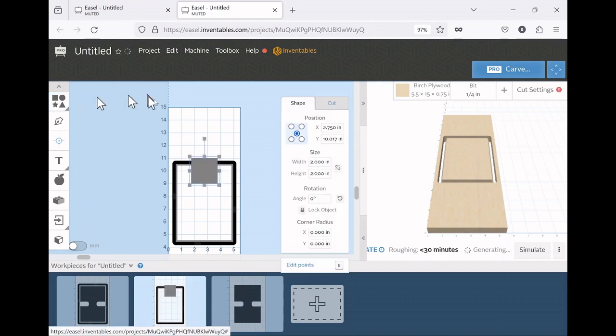All right, we're going to now cut out this area in the center, and we're going to do that by creating a rectangle, the last rectangle, number 8. The rectangle is 4 1/8 wide, 4.125, and it's 5 7/8 high, 5.875, excuse me.